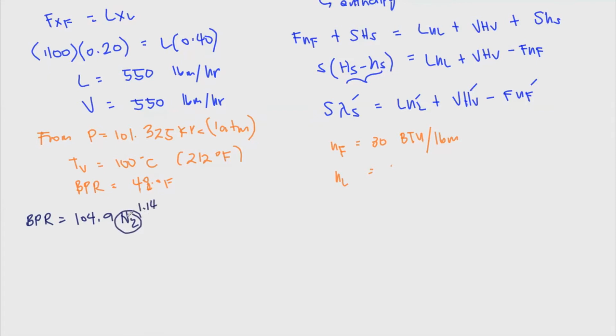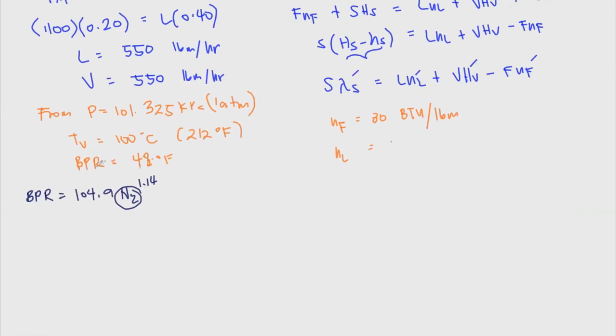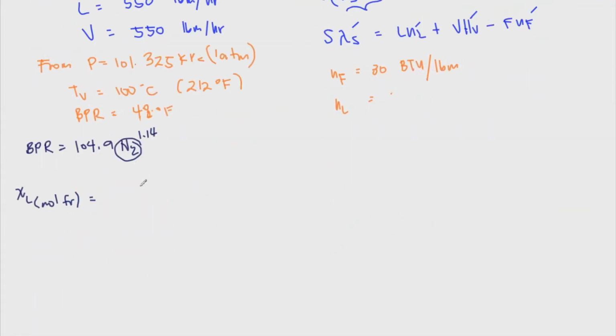Now this n sub 2 is the mole fraction of your liquor. So let's try using 40% in this case. So we need to convert that into mole fraction. So let's have this XL mole fraction, that is equal to, let's say we have 40 grams of sodium hydroxide, and then we divide, of course, by 40 grams, that's 1 mole, because that's the molecular weight of sodium hydroxide, and then we have 40 over 40 as well, and then since it's 40, we have 60 for this, and then divide by 18.